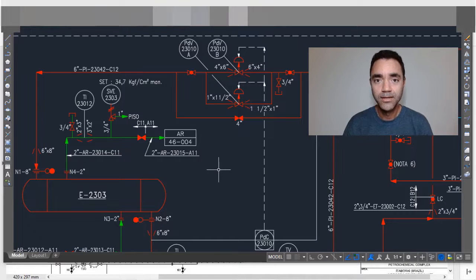Now you are seeing another P&ID with different standards for the drawing, and it is also another process. But the concept is the same, and in this case what we have here is a controller and pressure differential valves to control the differential pressure between what is going upstream of the heat exchanger and going out at downstream of the heat exchanger.